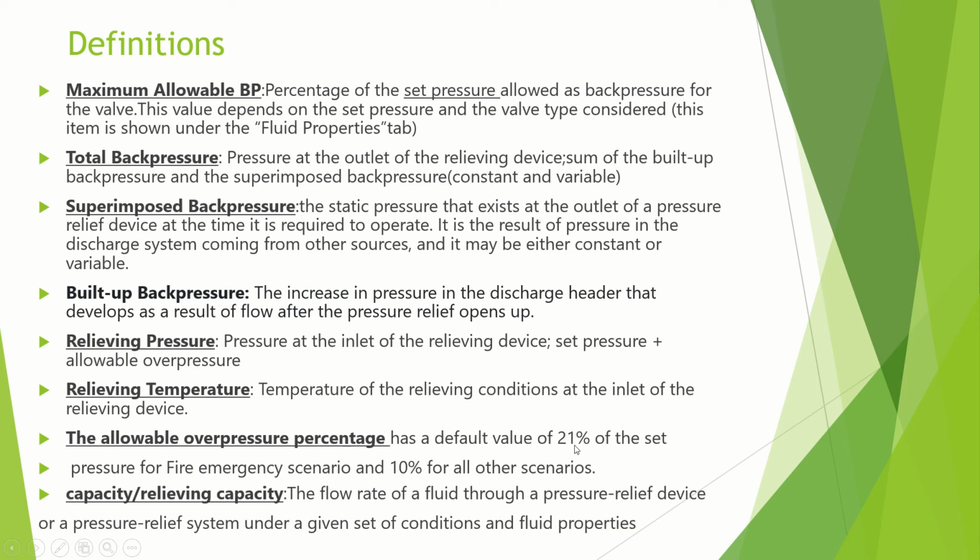It is 21% of the set pressure for a fire emergency scenario and 10% for all other scenarios. The other definition is the relieving capacity, which is the flow rate of a fluid through a pressure relief device or a pressure relief system under the given set conditions and fluid properties.